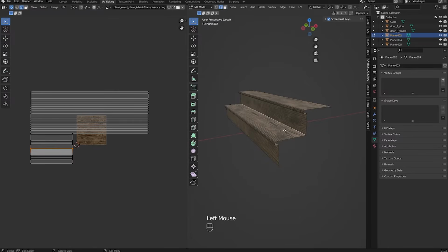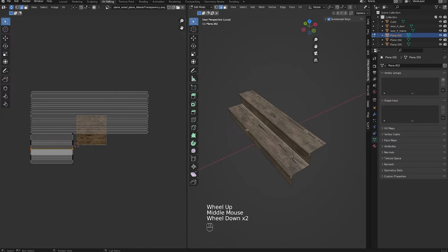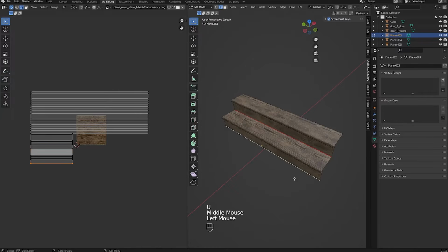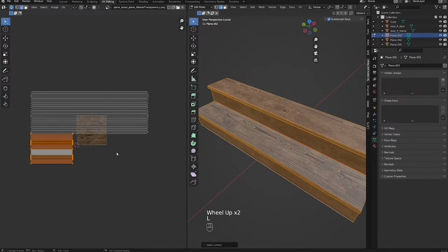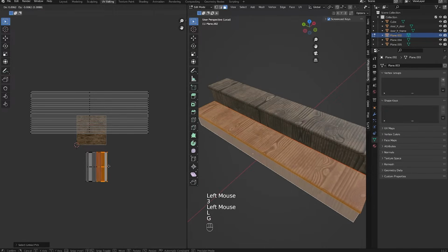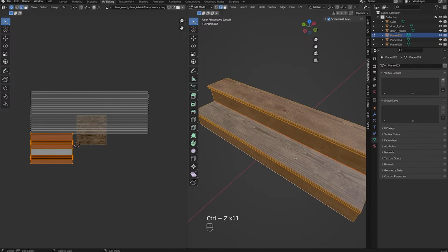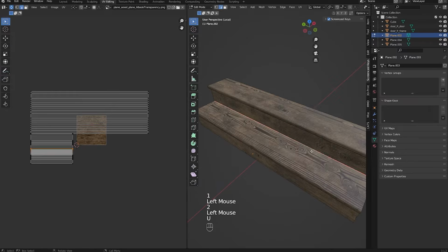Now, we're going to do this with the next 3D mesh, but just to give you an idea of what happens when we add seams. When we add seams, the seams basically tell the program to cut the mesh here so that it can unwrap better. It's not needed for this object, but just for demonstration purposes, let's in edge select an edge, and I'm going to press mark seam, and it's going to turn red. Then if I select this object and press U, unwrap, now there are 2 objects here unwrapped. So that's what seams do, and that's going to be important for the next mesh, which you'll see. So I'm just going to select this and get rid of that.